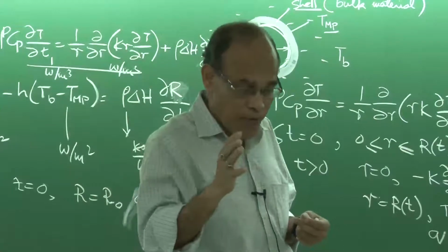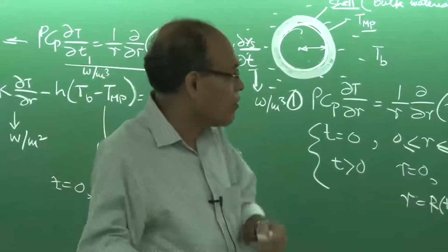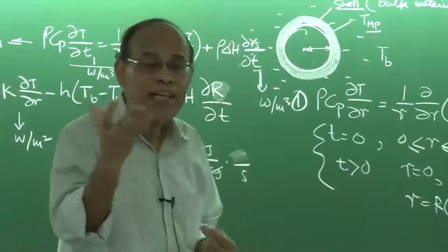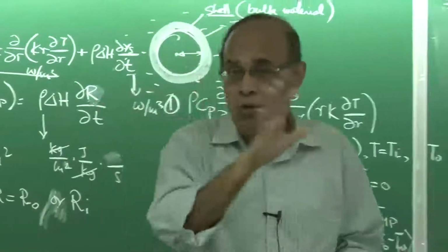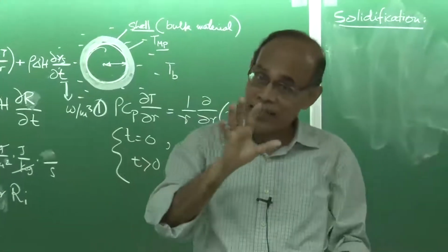And once solidification is complete, then comes the solid cooling stage. So superheat removal basically takes place in the liquid state itself. There is no phase change involved. Heat is being extracted, but still the material is in a liquid phase.